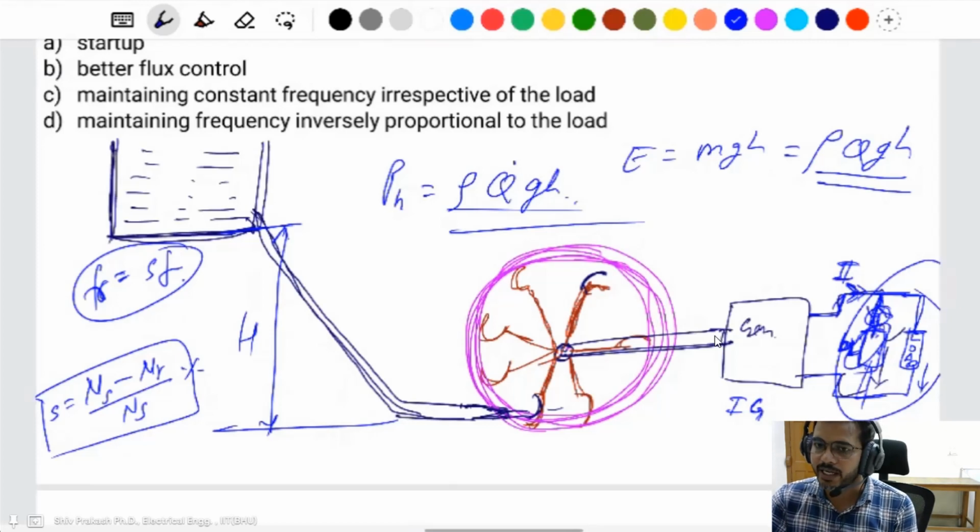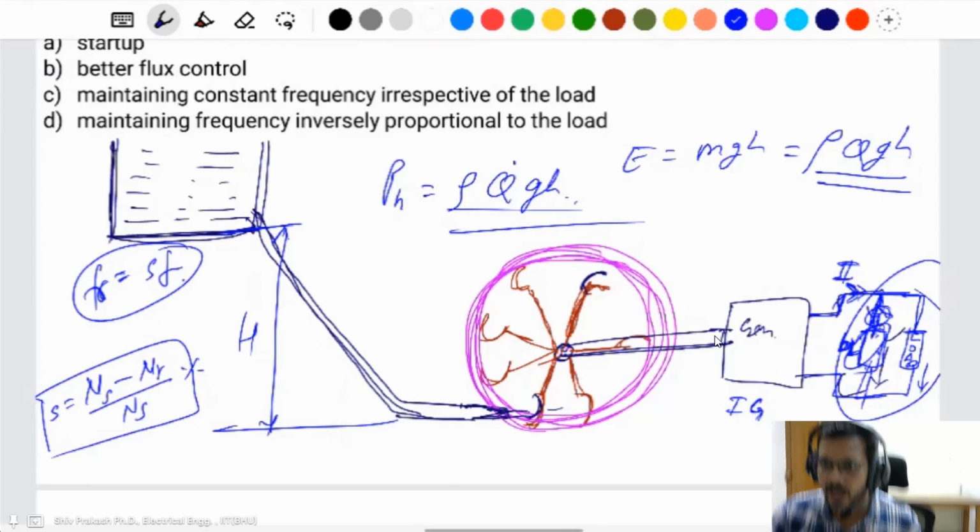Then the inverter maintains 50 hertz only, with some voltage. In a large-scale stand-alone system, this would be highly costly because of the converter. That's why it is connected directly to the load, and you connect a ballast load in parallel to the load to maintain a constant frequency when the load varies.